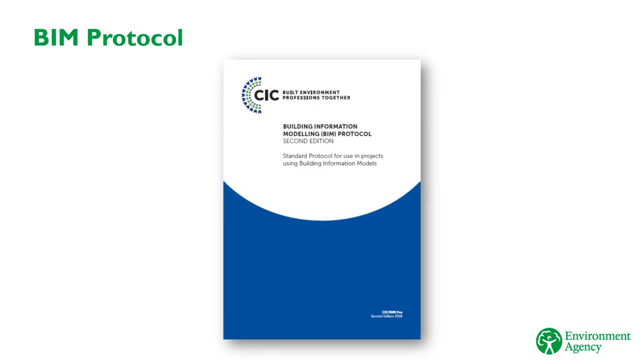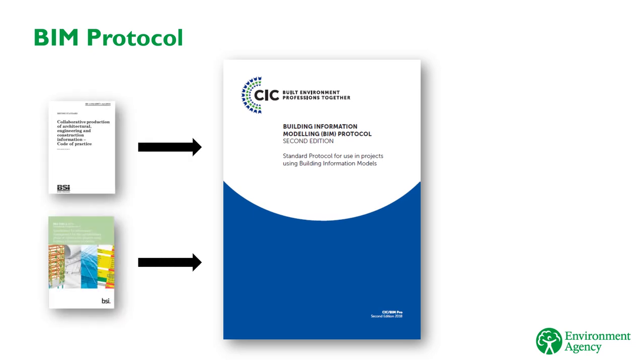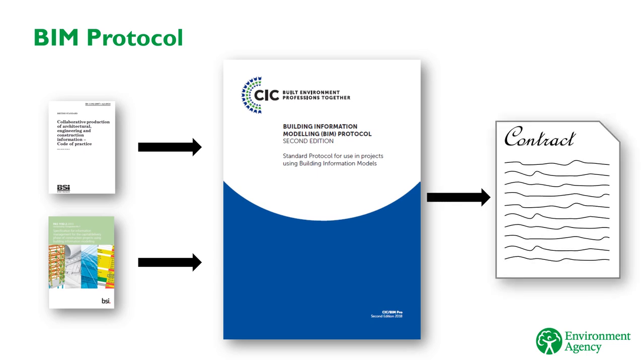The BIM Protocol was developed by the Construction Industry Council in 2013 and updated in 2018. It's a legal agreement which has been designed to be included with construction contracts in order to add BIM as a contractual requirement. In essence, it takes the roles, requirements, and processes that are described in BS1192 and PAS1192 Part 2 and creates contractual obligations on the employer and the supplier to undertake the roles and follow the processes. This means you can add BIM to the contract simply by referencing the BIM Protocol as an appendix. For Environment Agency contracts, the standard contract documents we use for most of our commissions have been updated to include a provision which attaches the BIM Protocol.